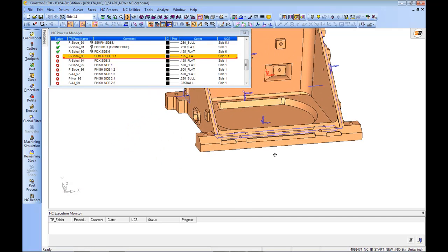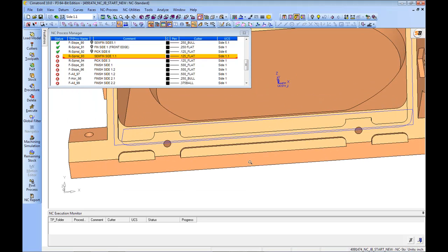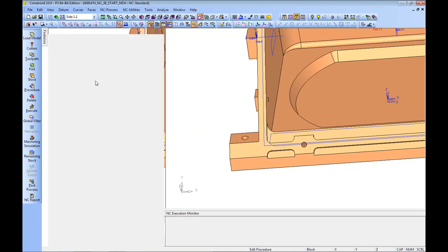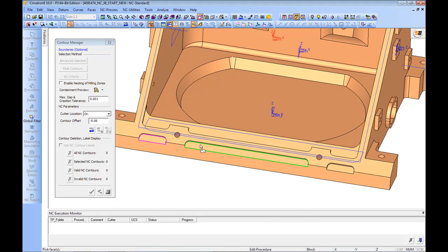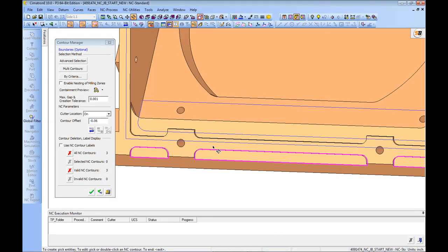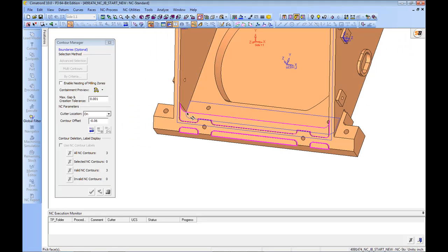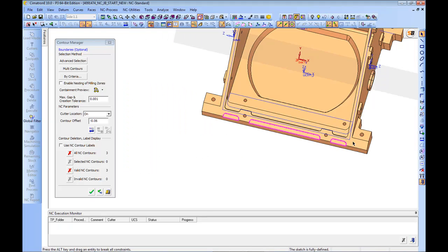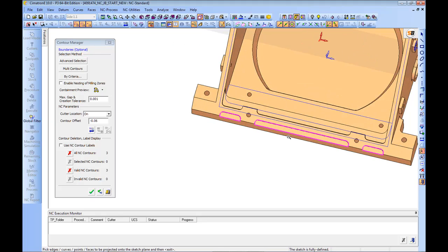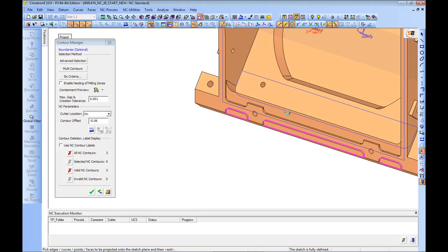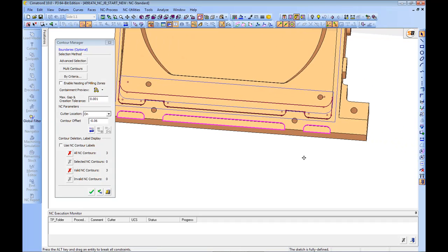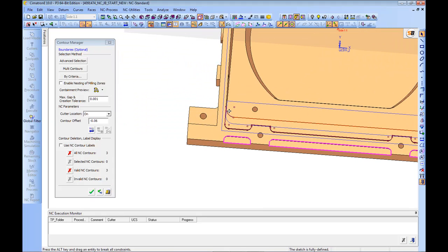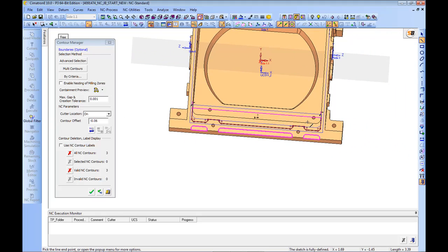And what we're trying to do right now is take care of these guys here. So let's go into this one, and when we go to boundaries, we can also pick floors. So watch me pick these boundaries by indicating these floors. I could probably pick this one, but I wouldn't like the way that that looks, so I'm not going to do that one. We'll do it like that, and then I'll go into the sketcher for this face. If I choose add geometry, I can pick this whole face, and I get all those boundaries to come in, and I'm just going to delete these two and then reconnect the lines from here to there.